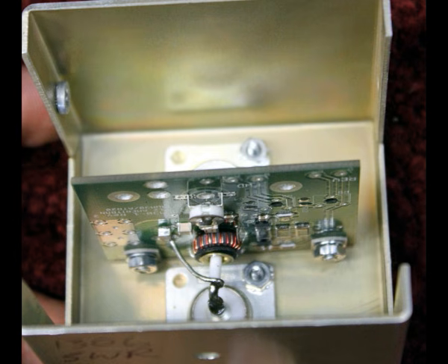And knowing the sum and the difference between those two things tells you how far you are off on impedance. But again, this particular directional coupler, while it can measure the power coming back one way and the forward power going the other way, isn't actually what it's measuring in the transmission line, because we really don't have reflected power flowing backwards into the source.